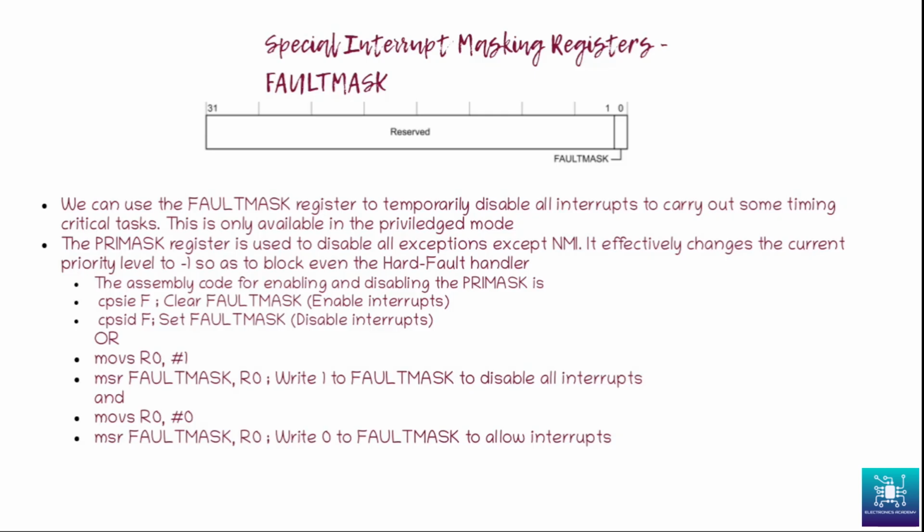Now, the reason why you would want to mask all the interrupts is for time critical tasks. That is one thing, and secondly, for shared resources.